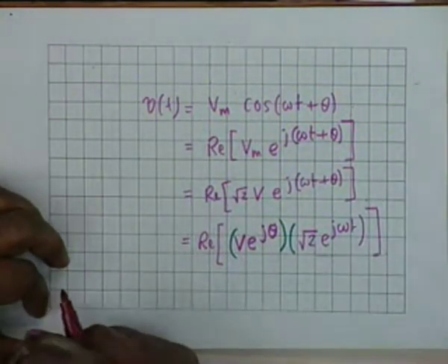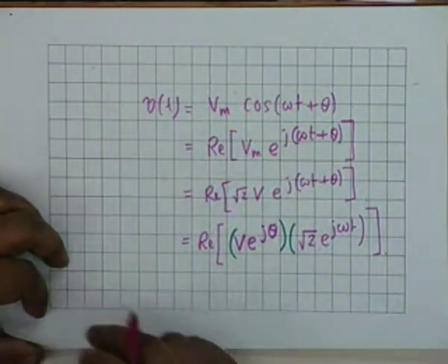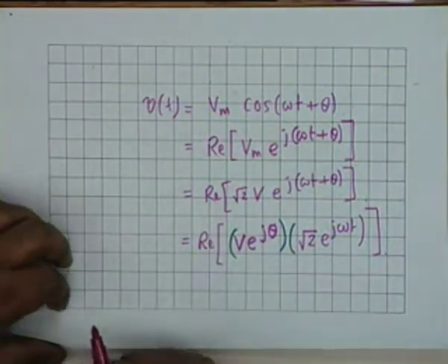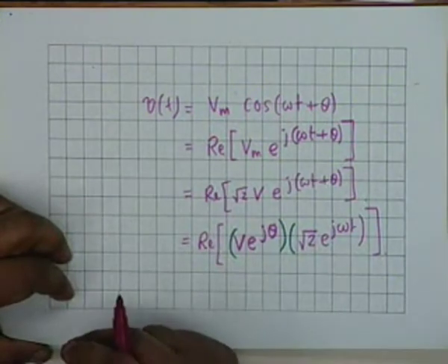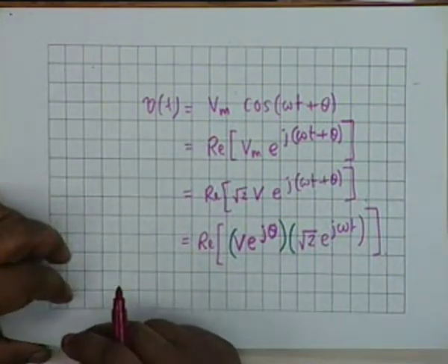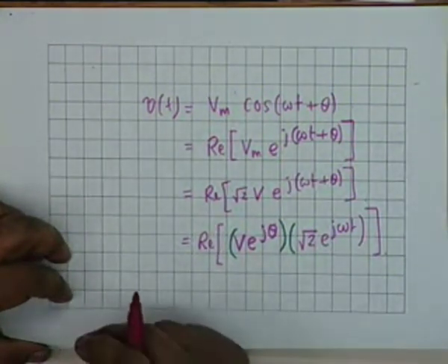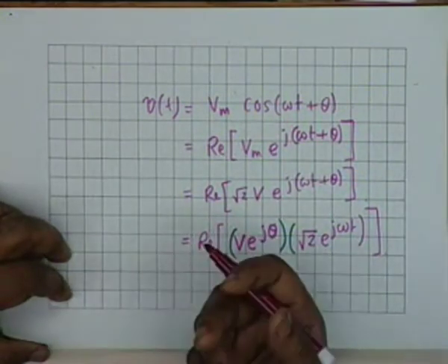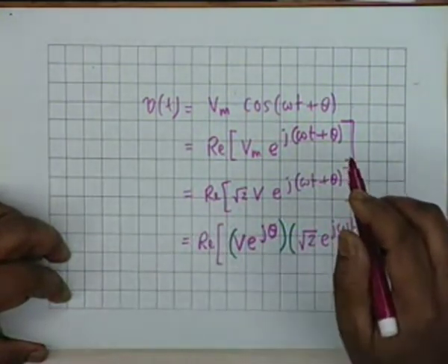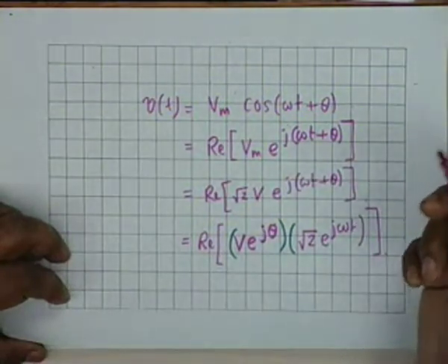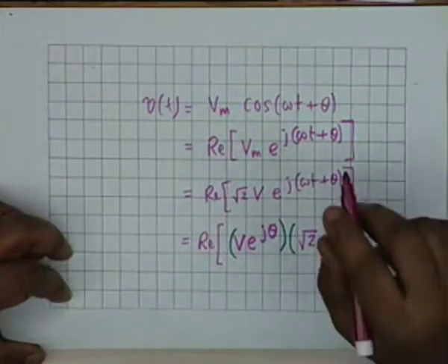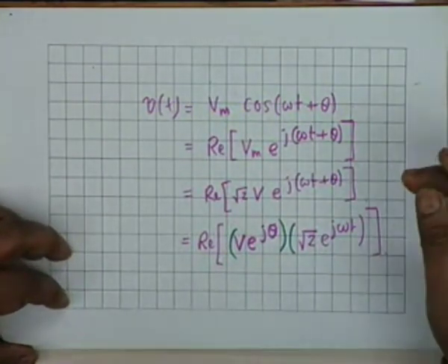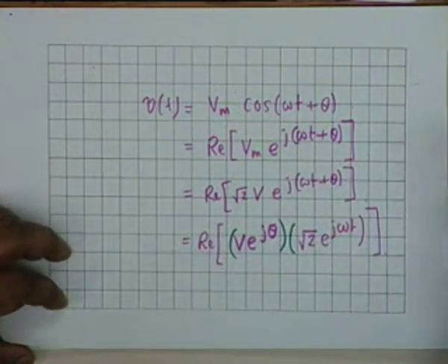all right. Now if this voltage is applied to a linear electrical circuit containing resistors, capacitors and inductors, then all currents and voltages shall be sinusoidal. You will be able to write them as some constant multiplied by cosine omega t plus some other constant phi, or sine omega t plus phi, all right.